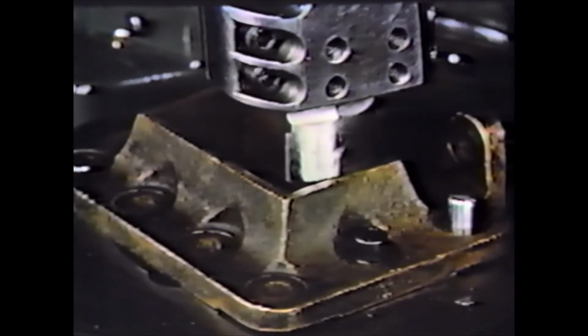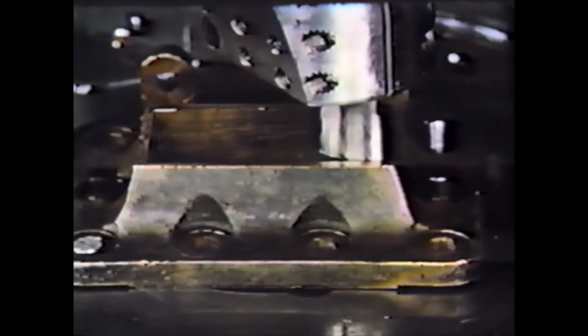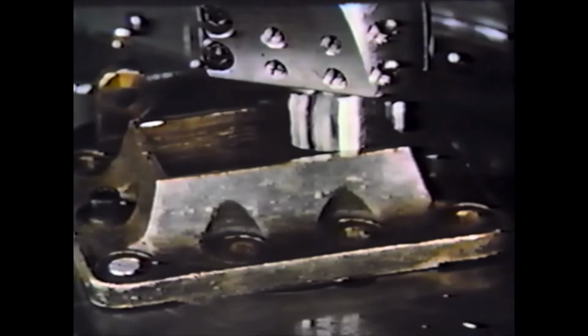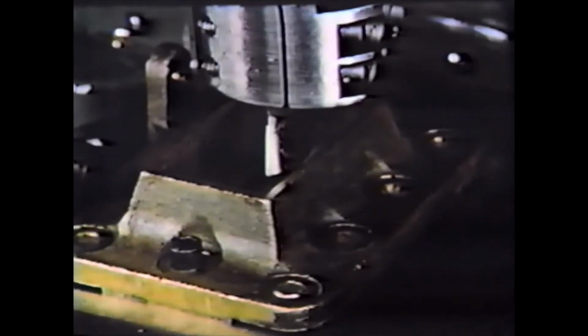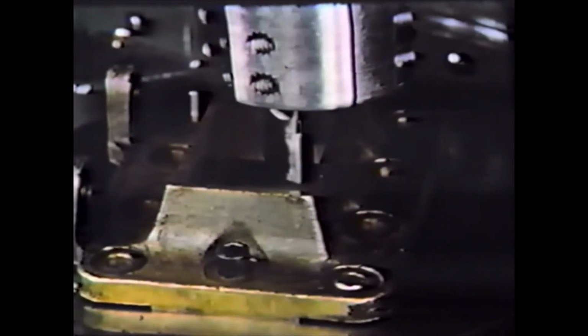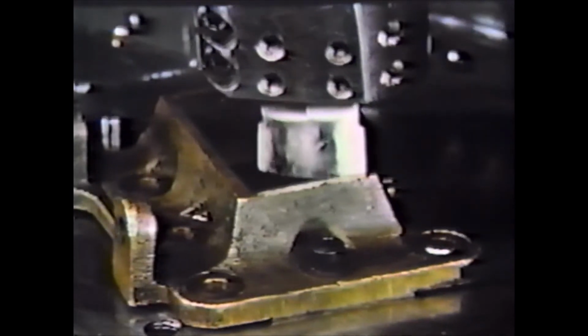The action of the cutter can be shown more clearly if we stop cutter reciprocation and rapidly rotate cutter and work. The cutter is set off-center in its holder and thus travels faster to finish the long sides than the short ones. When finishing the long surfaces, the cutter skids to make up for the difference in length of the long sides and the length of the arc on the cutter.